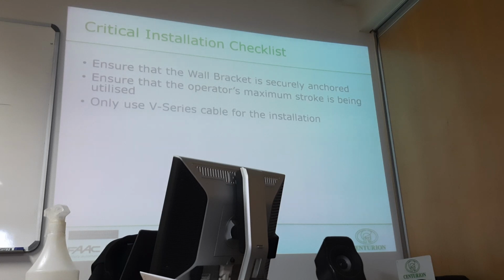I've seen so many sites where the client or the installer didn't use our Vector or V series cable, which is a 6-core and it's shielded. Unfortunately, I have a little piece somewhere, but I'm not sure. Someone cleaned it yesterday afternoon. But this cable has a thin foil type of screen in it, so it prevents any interference from the electric fence, which is our main culprit, or any mechanical interference to this controller.